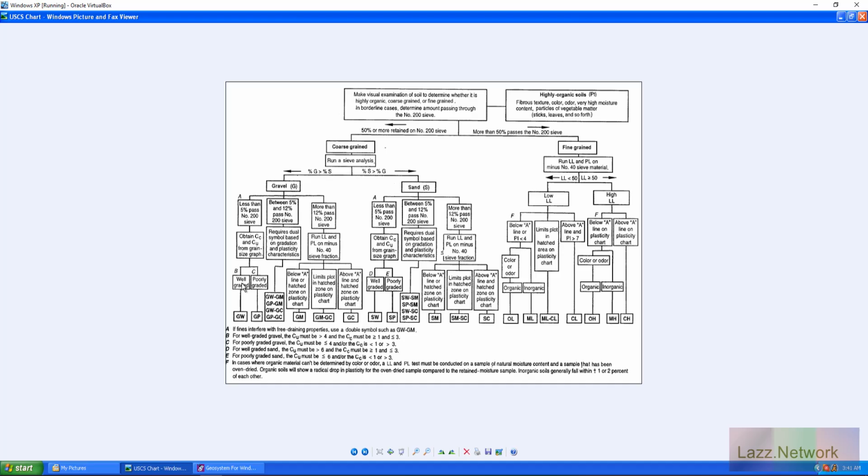Okay, that's the only catch when it comes to classifying things. Most of the time your material is usually poorly graded anyway. If it's coming from a pit or the ground or anything like that, it's usually poorly graded. It's just naturally occurring material that is there. So, well graded material is material that has been manipulated and engineered in a way for it to become well graded. So things like asphalt and concrete,